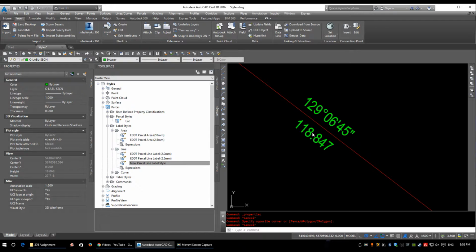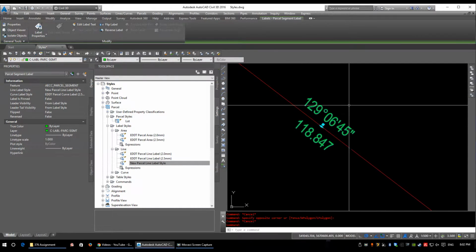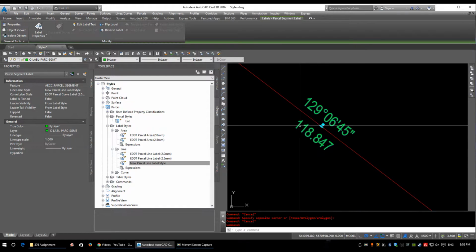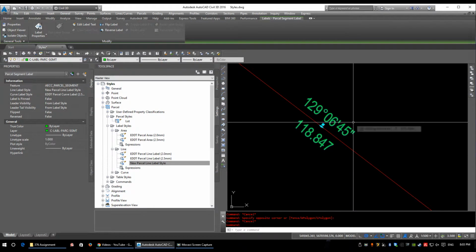Now, if you're using a simple text like Simplex, that will pick up your line weight thicknesses. So if you're using color white in, for example, my CTB file, it's 0.7 or 0.9 thickness. It prints really bold. So as long as you have a true type font, you don't need to worry about what color your objects are on. Now, if they are on a color that prints in color, so if you want something to actually print red, then, for example, in my template, I'd use color 10. That will print red. Color 1 will just print black. So no line thicknesses, no line weights, but color, it does take over.